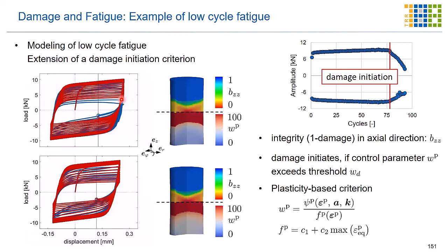So you see one slope here from the start, and the slopes are also decreasing because the elastic moduli are decreasing at the end. Also, you see that the maximum load here from the experiment can be transferred to a maximum stress, and this means that you also have an influence of damage that evolves during the cycles on the plastic limit here, on the limit.